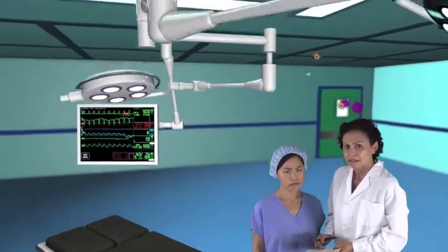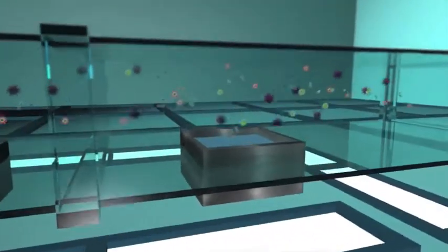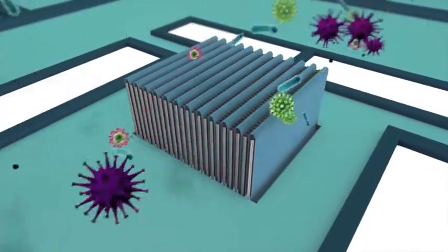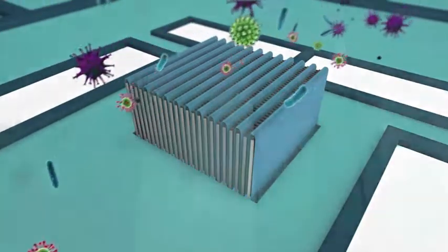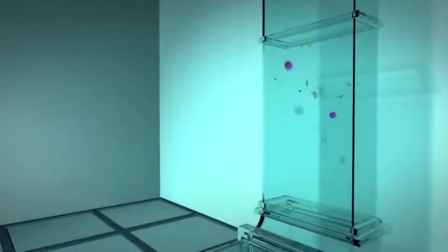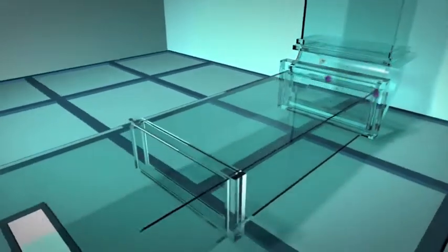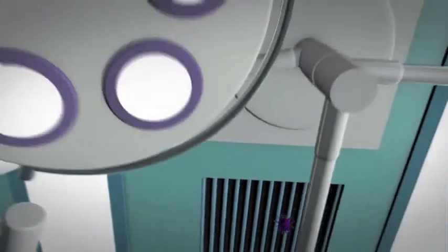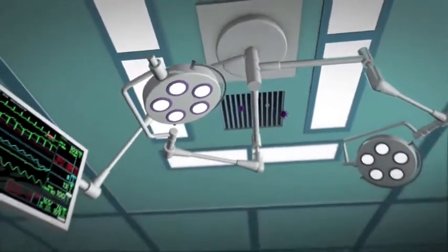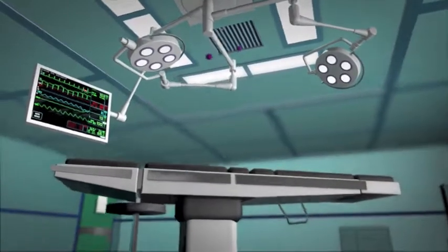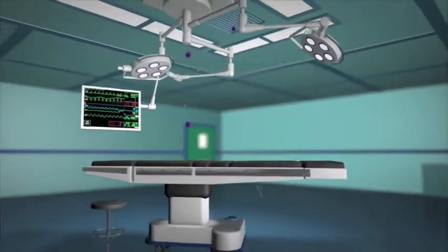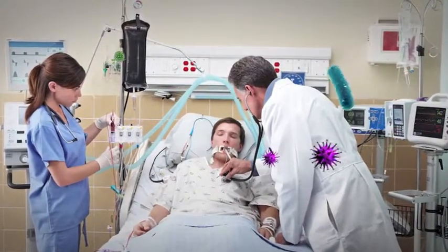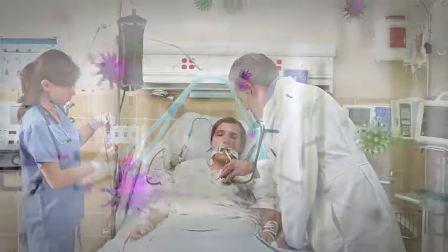Hospitals feel protected by the use of HEPA filters that block up to 99.97% of particulates. However, 1 cubic foot of air typically contains 100,000 microparticles. With air traveling at approximately 800 feet per minute through a 24-inch square duct, we have 80 million particles. So, on average, 0.003%, or 24,000 of the particles per minute, might break through the HEPA filter. If only some microorganisms break through, they can infect the patients.